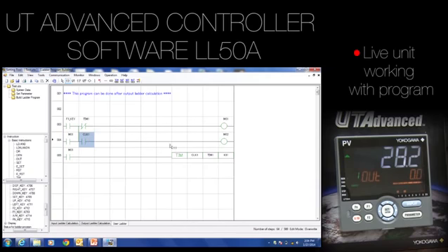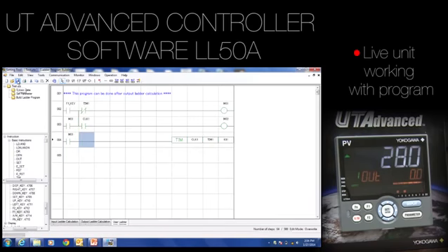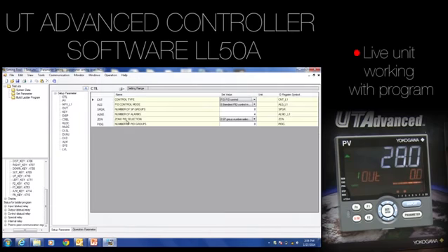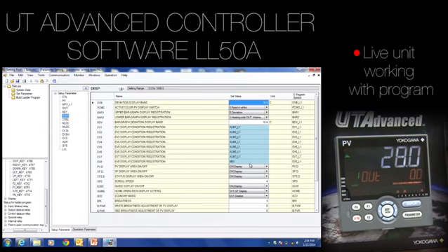M02 is going to be the clock frequency, so it's just going to pulse on and off as long as M01 is pulled in and the timer hasn't elapsed. So it's getting to be a little complicated, but you can show the power in the controller. So let's go ahead and save this. The other thing we need to do is change that display lamp from M01 to M02. So let's go do that. Display M01 there. Change that to M02.